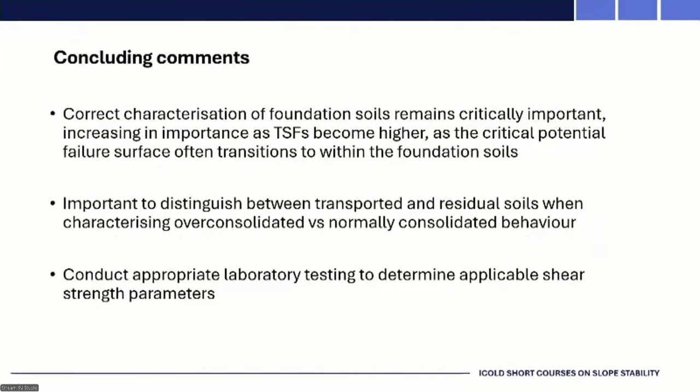Okay, I think that's just about it. I think correctly characterizing foundations has sometimes been a little bit neglected or put to the side. I think it's critically important, particularly as the dams get higher, because this is where the failure surface often transitions to being mainly located within the foundation. We need to distinguish between transported and residual soils. For some people that's old news, but for some people clearly not.